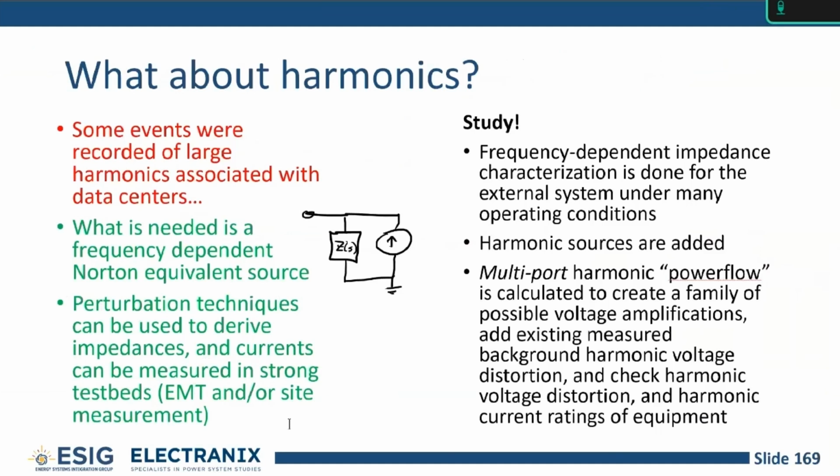For those who are actually interested in harmonics, so Amir, one of the problems we've had with this, a practical problem, and this actually is a practical problem with what's recommended in IEEE 2800, is that trying to do these frequency scans or trying to measure the harmonic impedances of the devices is very hard if the impedance is time varying in the device, which it turned out to be in some cases. So if it has a constant impedance at some frequency, we can measure that and use it in the study. But if it turns out some of these power supplies, for example, actually their impedances are varying with time, which means we can't measure them properly.